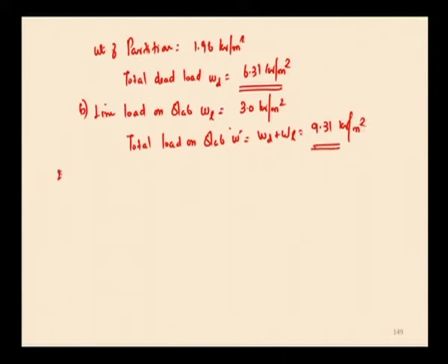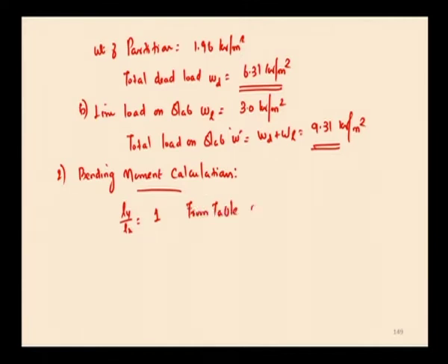Next, second step, bending moment calculation. In the case of bending moment, now we are going to use the table 26 to find the moment coefficients for the ratio Ly by Lx is equal to 1. So, from table 26 and with the condition of one long edge discontinuous.